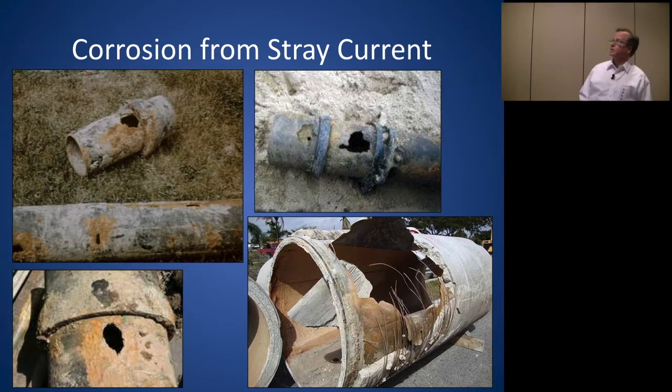That's what it looks like. What we've got here is stray current was moving this way down the pipe. It hit the resistance of this joint here and jumped through the soil to this and kept on going to its source. Where it jumps off the pipe to get around this joint, that's where your corrosion occurs. Same thing here. I can tell the current was going this direction to try to get back to its source because of where the corrosion is.